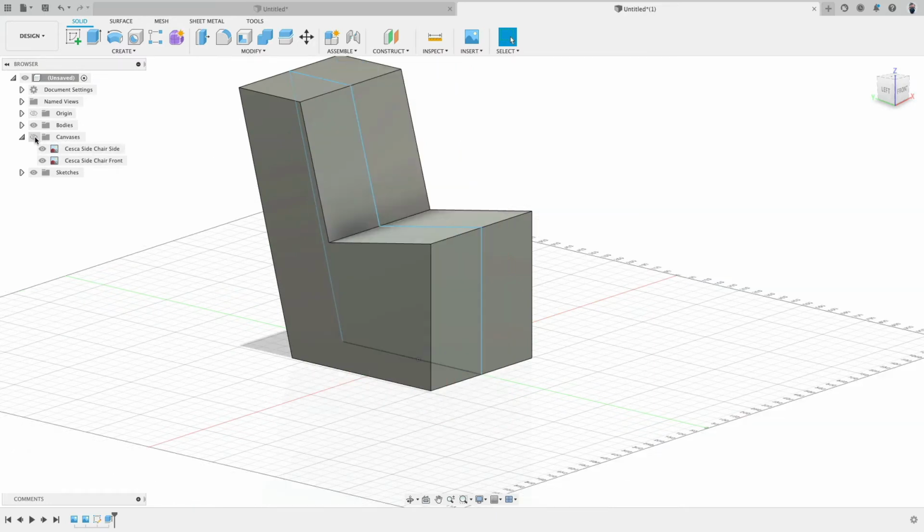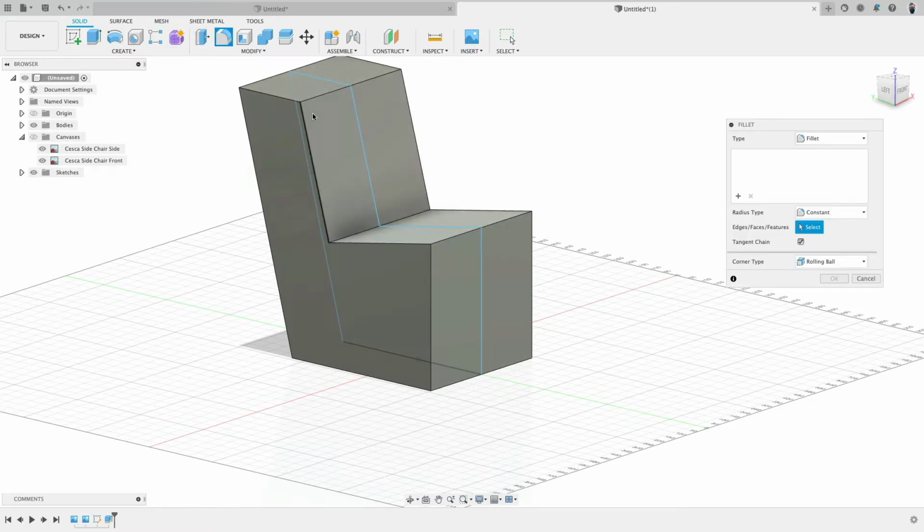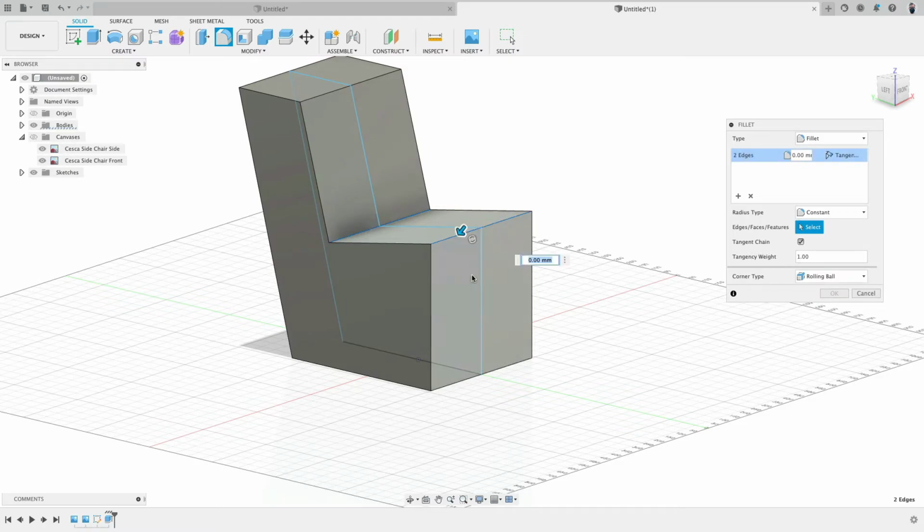And this is a really nice trick because to create this three-dimensional volume, and then we treat the edges so we can use the edges to run a pipe along. Because making pipes in 3D can be quite complicated with a lot of sketches. It's kind of like a lot of work, and I find this much easier to do simply a volume model. So we will start with the fillet command. We will select these edges.